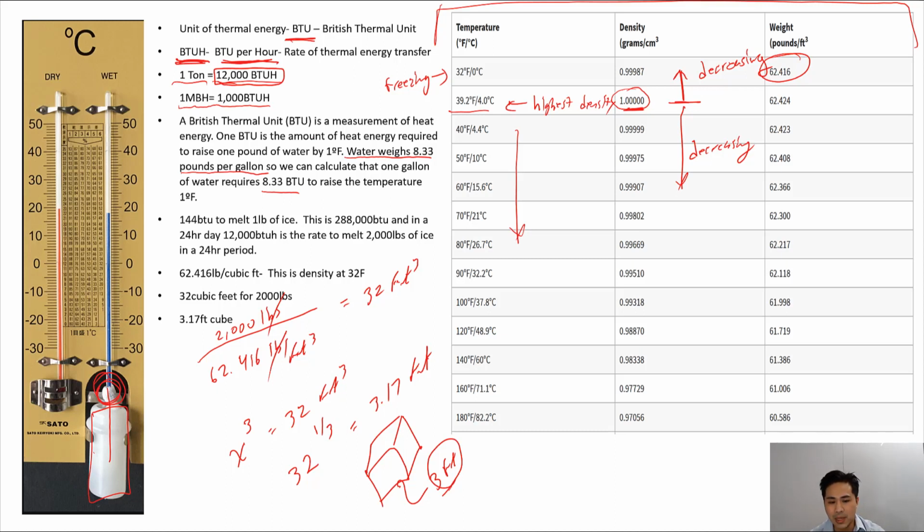Another way to understand the concept of wet bulb temperature is, if you are outdoors and you're sweating, the temperature of that sweat on your skin in that air is the wet bulb temperature. As you know, if it's less humid outside, your sweat would feel cooler than if it was more humid. We're going to look at the exact relationship between the dry bulb temperature, the wet bulb temperature, and the amount of humidity in the air when we look at a psychrometric chart in later videos.